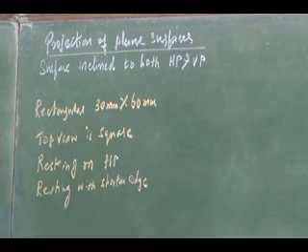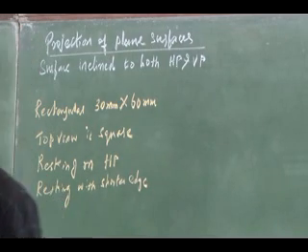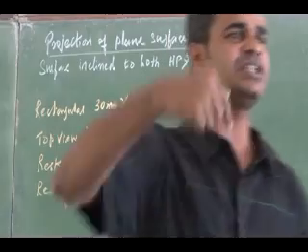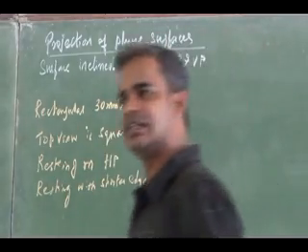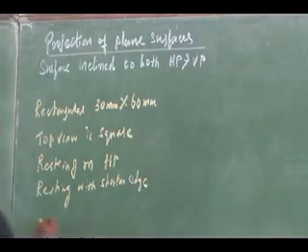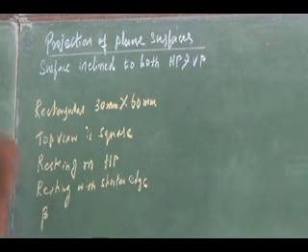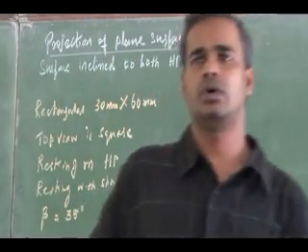Then the resting edge is inclined. Resting edge inclination to VP is nothing but the apparent inclination. So I have an apparent inclination to VP, which will be beta. VP apparent inclination is nothing but beta, that is 35 degree.